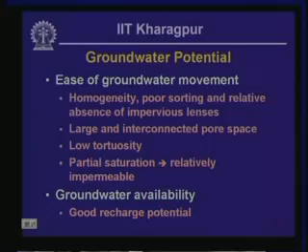So that type of soil does not act as a very good source of groundwater. And on the other hand, if you have got very thick massive formation of lacustrine clay, that is not going to conduct groundwater at all, and for all practical purposes such a deposit can be considered as an aquiclude.